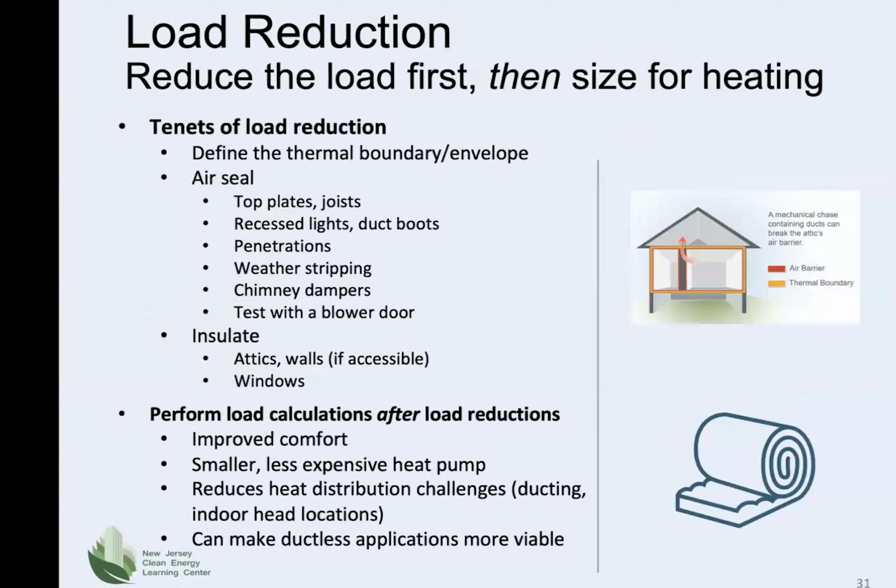This can allow for smaller and less expensive heat pumps and ensure the system is not oversized for the home's actual need. This will also make it easier to match available heat pumps to the home's overall load and energy need across all conditions. A leaky, high-load house requires a larger heat pump to cover the peak heating need, which inevitably leads to an oversized heat pump for mild conditions. More on that dynamic later in the presentation.